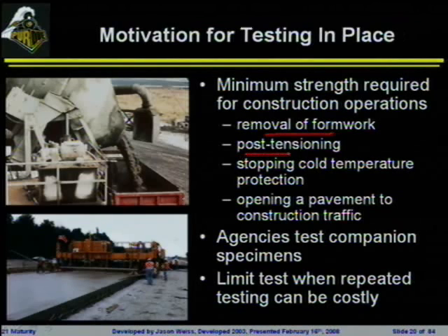When are we going to be able to post-tension our concrete? We've got our concrete out there. It has to get a minimum strength before we can post-tension it. When can we start to go out and do some cold weather protection? When can we open a pavement to construction traffic? There are a lot of different questions here that can be asked if you have some indication of how fast that concrete is gaining strength.